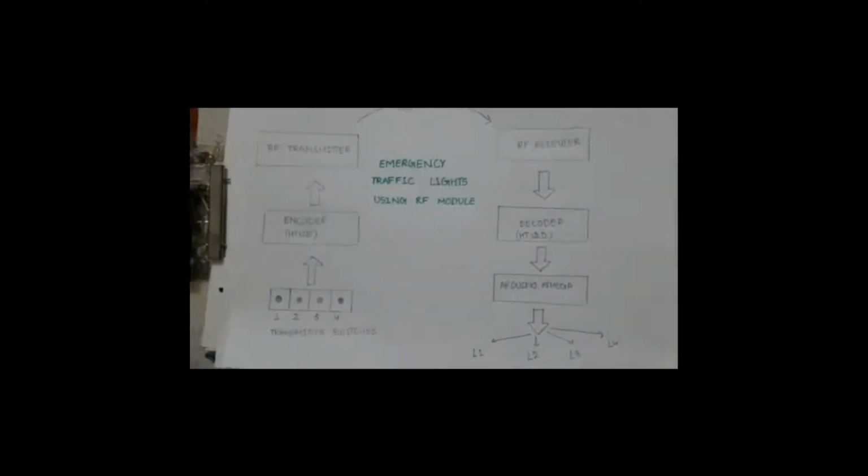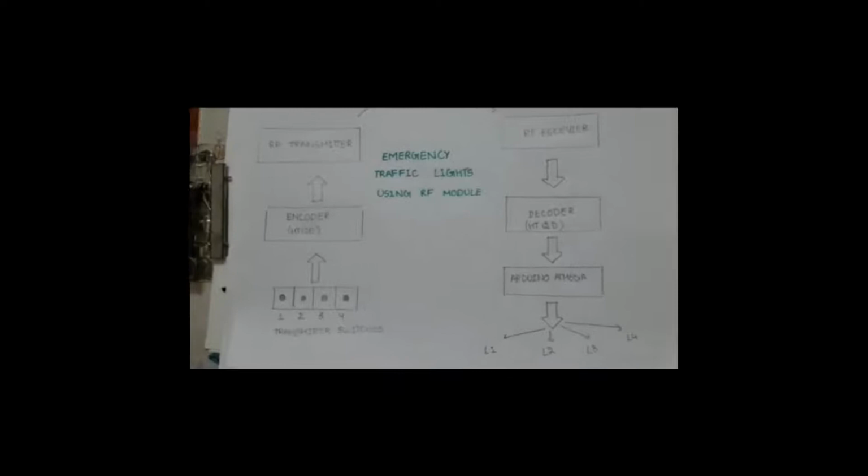Amplitude shift keying is sometimes also called binary amplitude shift modulation, as there are only 2 levels to be concerned with: the digital 1, which drives the carrier at full strength, and the digital 0, which cuts the carrier off completely. ASK has the advantage of being very simple, so the resulting circuitry is simple and inexpensive. The disadvantage is that ASK is susceptible to interference from other radio devices and background noises.